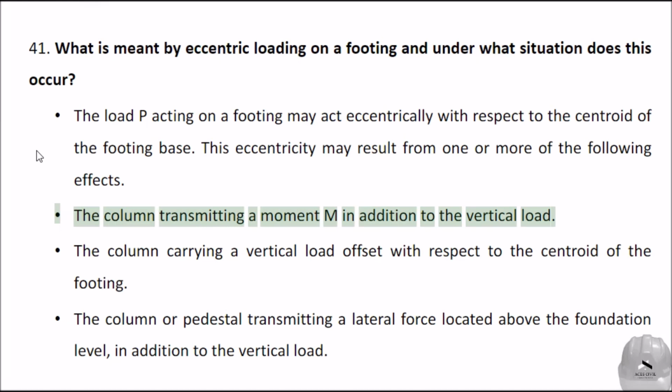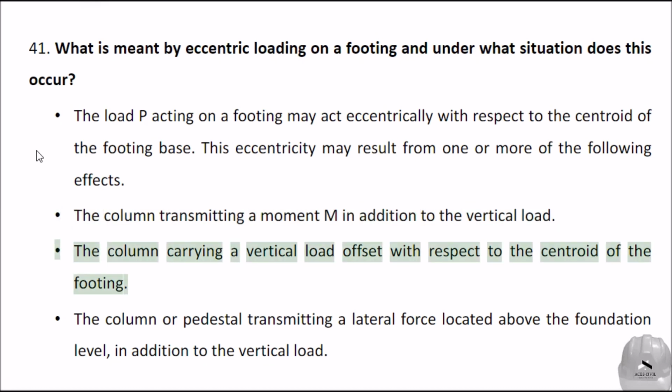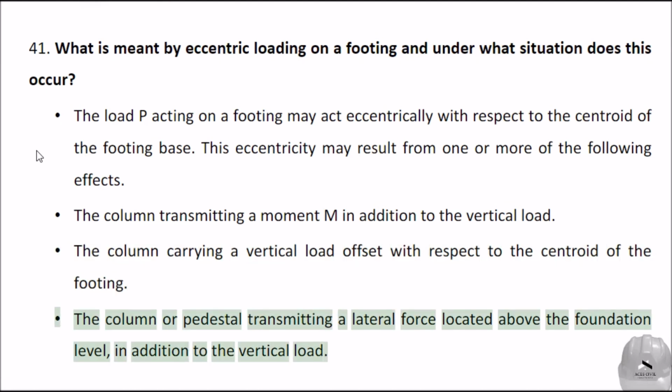The column transmitting a moment M in addition to the vertical load. The column carrying a vertical load offset with respect to the centroid of the footing. The column or pedestal transmitting a lateral force located above the foundation level, in addition to the vertical load.